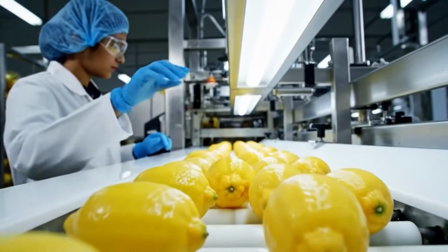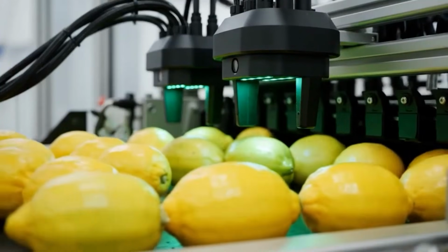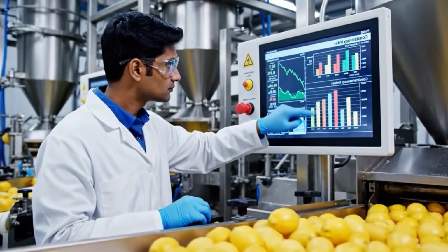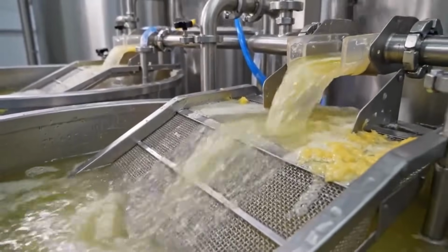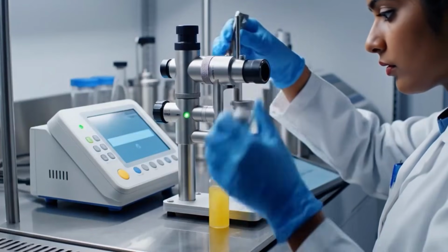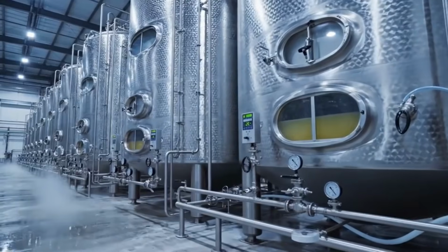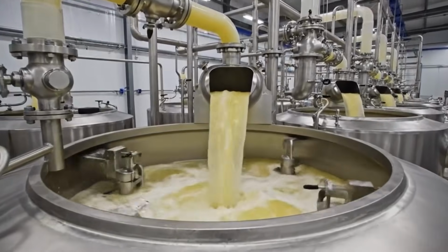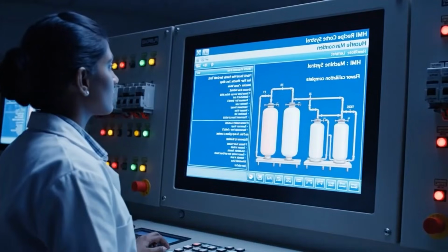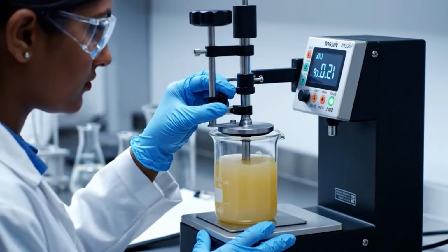Production lines are modular and allow for multiple flavor variants and packaging formats. Line changeovers are performed by CIP, clean-in-place cycles, product purges, and recipe uploads via the SCADA interface. Automated valves and sensor diagnostics reduce downtime between batches. Lines may produce up to 8,000 litres of finished sorbet per hour, depending on viscosity, inclusion complexity, and packaging speed.